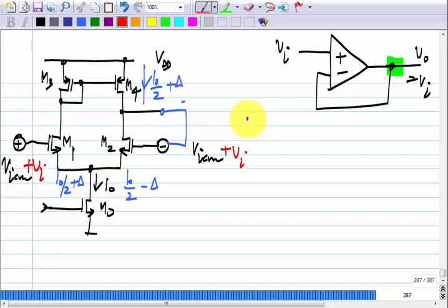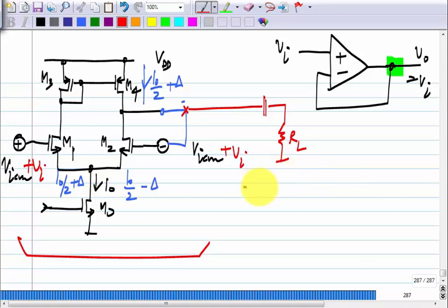buffer using an op amp, and this can be used. This is sometimes used. The point is, if you do have a resistive load, and just for simplicity, in order not to disturb the biasing, I will AC couple that. Okay. So, this is just so that I do not change the operating point here. What happens in this case? Yeah. So, first let us look at the small signal model of this alone without RL. What was it? The small signal model of the op amp.